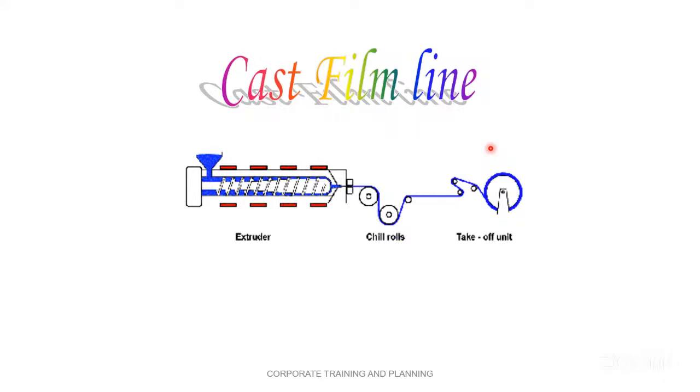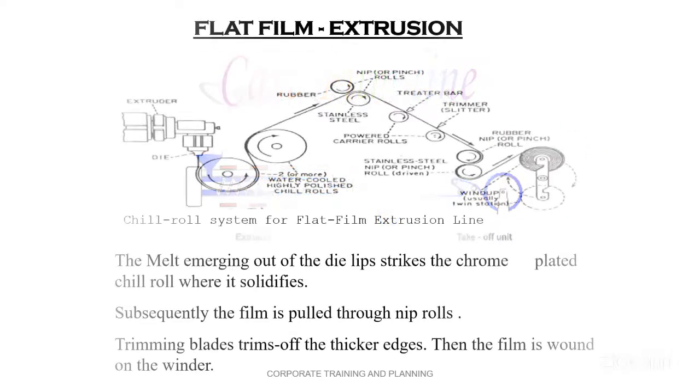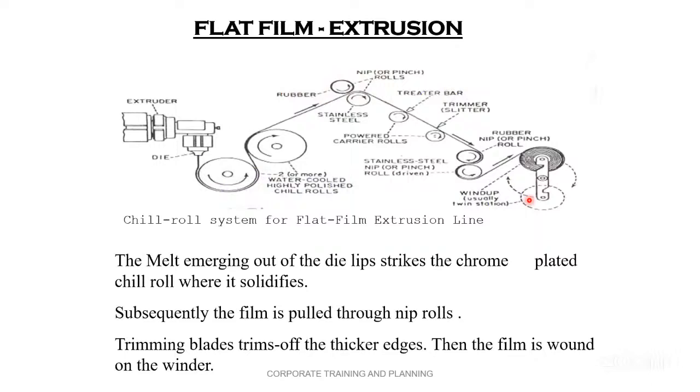Now the cast film frame, this is a very important plant. If you see here again, the material is cast here from the granules. Here see the extruder rotating continuously in the clockwise direction. Heaters are provided on the barrel. There is a cast film die, friend. It is also at a 90 degree angle, right? There is a take up roll. This is a floating roll here. These are guiding rolls. This is what the center winding is here, friend. Now see the structure of this.